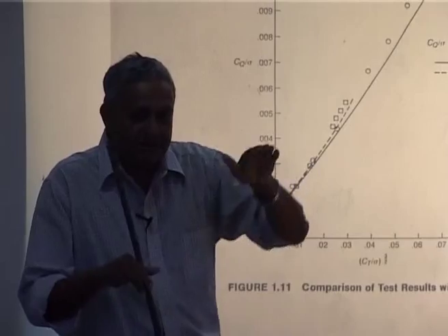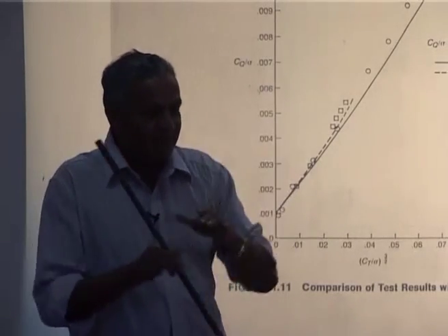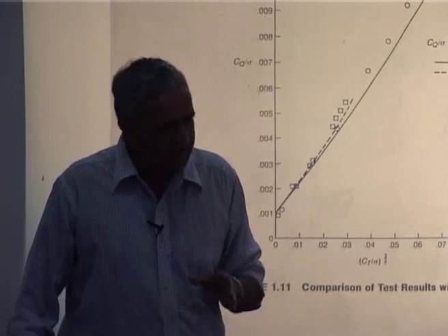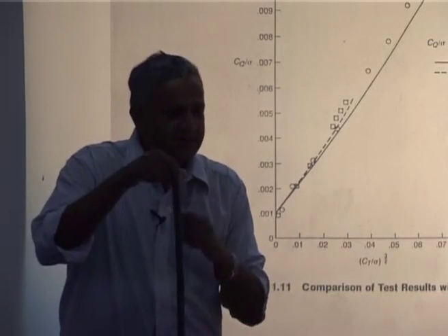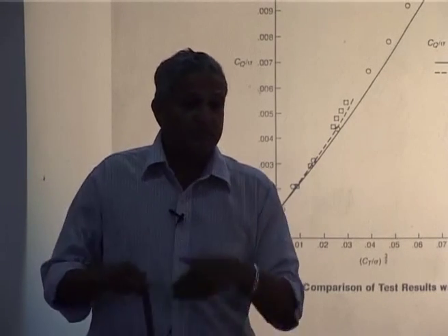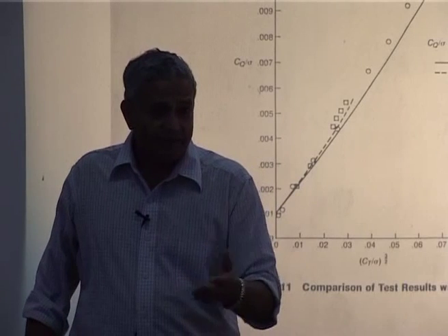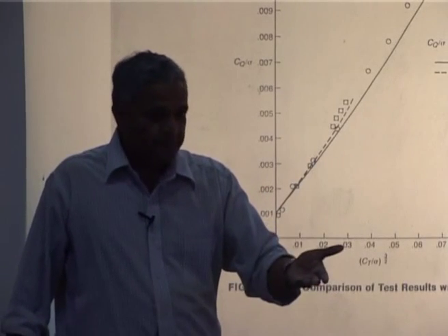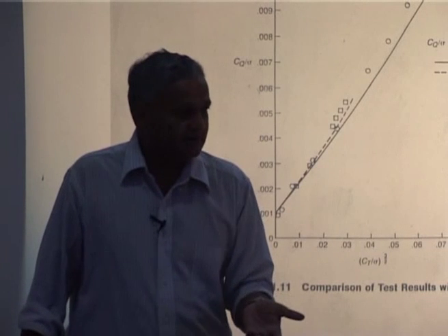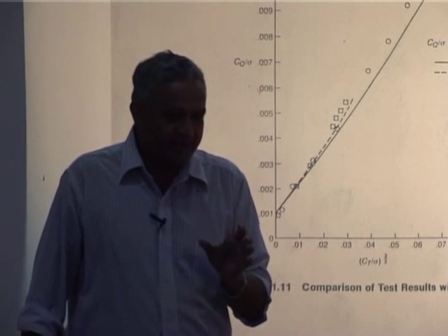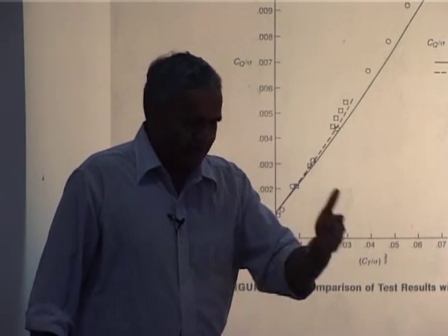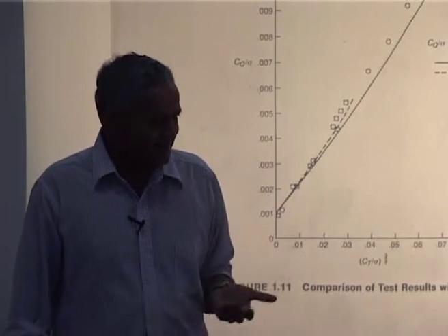So this is how they try to come up with some kind of a limit of the rotor, because in certain operations, Ct by sigma and everything is fine, but the pitch link load will go up to such an extent, or sometimes the vibration will go to a high value, that the pilot will not be able to operate the vehicle. That is why it is very interesting to see, because this is based on my discussion with the industry people.